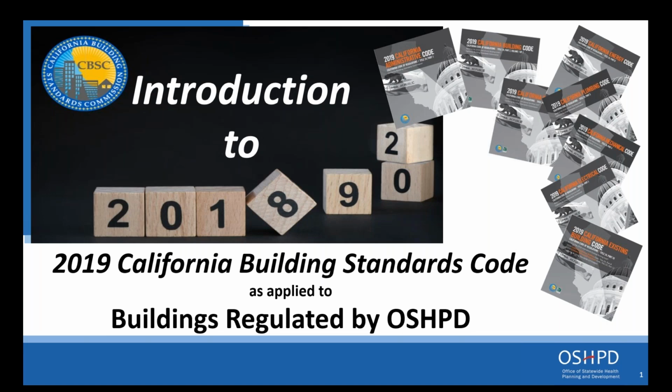You start doing the math, you go down that rabbit hole. And what you find is when you go to 62.1, you have these factors like R sub A, A sub P, D for diversity, ventilation efficiency, E sub V, and you realize those factors are not established for healthcare. So now what do you do? Well, you end up with something that's very soft and willy-nilly, it's very difficult to enforce, and you can't establish minimums for your outdoor air intakes.